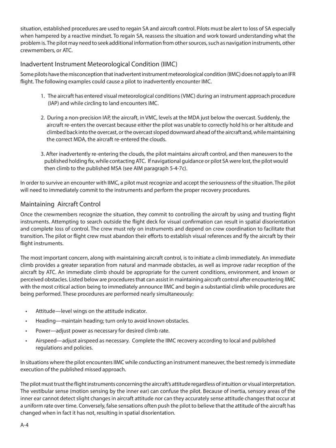Inadvertent instrument meteorological condition, IIMC. Some pilots have the misconception that inadvertent instrument meteorological condition, IIMC, does not apply to an IFR flight. The following examples could cause a pilot to inadvertently encounter IMC. 1. The aircraft has entered visual meteorological conditions, VMC, during an instrument approach procedure, IAP, and while circling to land encounters IMC. 2. During a non-precision IAP, the aircraft, in VMC, levels at the MDA just below the overcast.